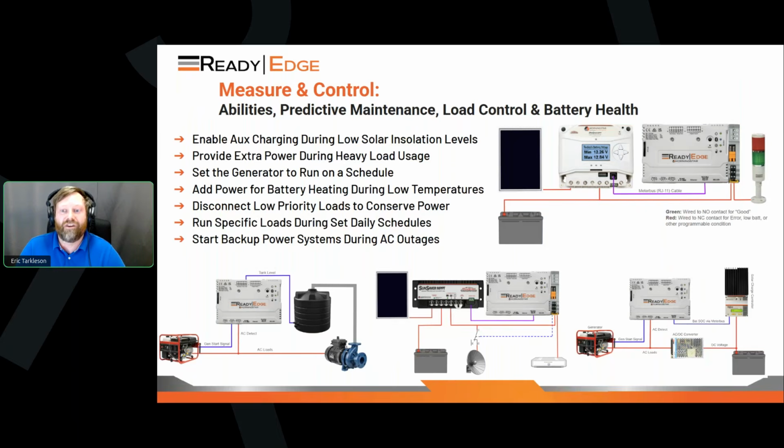You can have the generator or your loads run on a schedule. You can do battery heating. Save your money on the lithium batteries with heaters and just buy a heating mat. Put it under the battery. You're going to get a lot more control as to how and when to heat this battery. And then a lot of load scheduling and load disconnect possibilities with the ReadyEdge, especially with the expandability with the Ready Relay. We'll talk a lot about that.